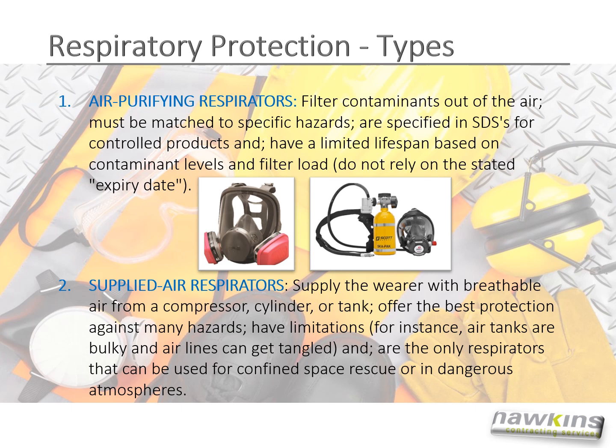They must be matched to specific hazards, are specified in SDSs for controlled products, and have a limited lifespan based on contaminant levels and filter load. Do not rely on the stated expiry date.